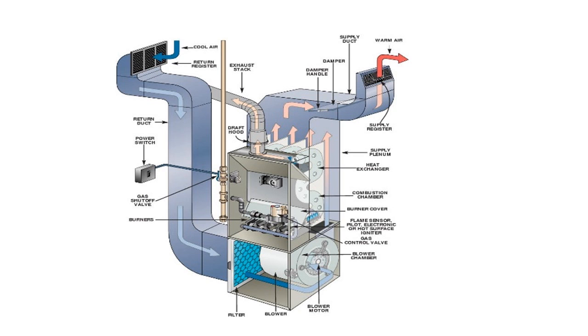A non-condensing furnace can be vented out a chimney. It will utilize a metal flue pipe to vent its combustion gases. Since they use only one heat exchanger, they will not have a pipe to drain condensate, and they are much less efficient than a condensing furnace.